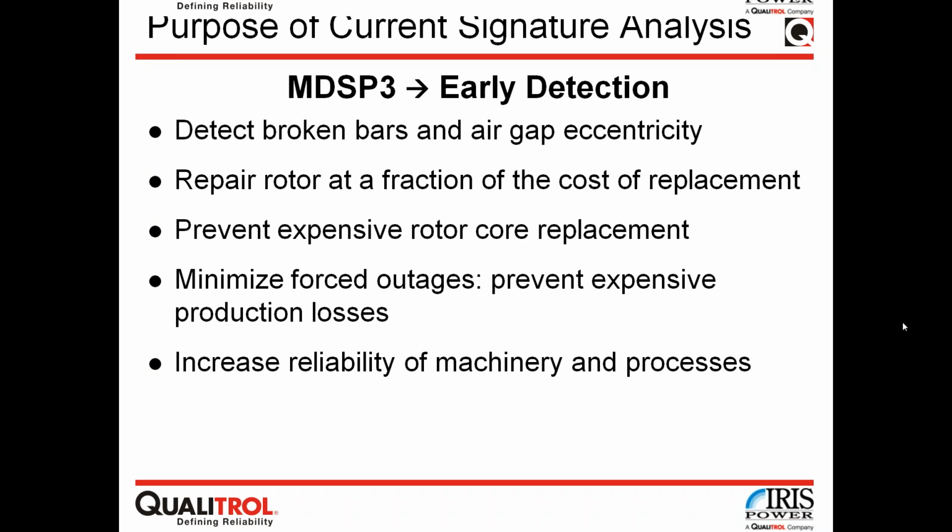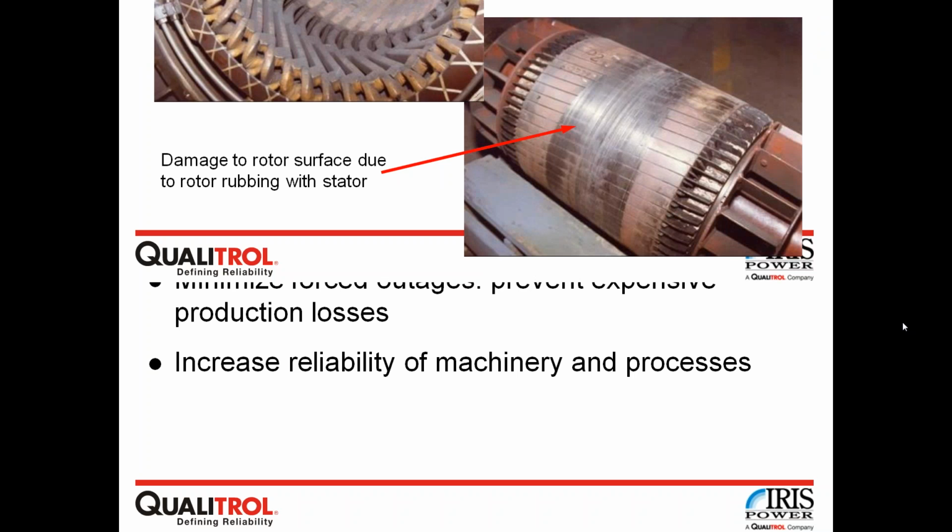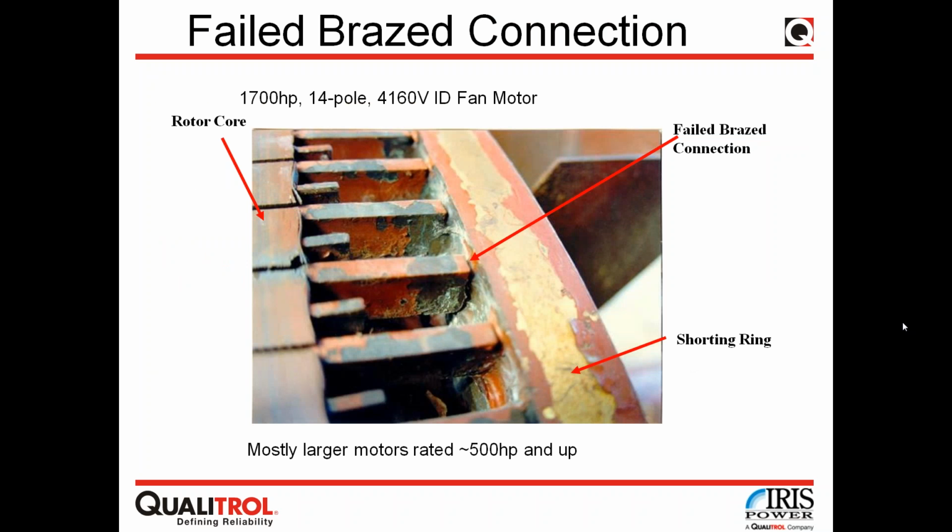Okay. It says offline rotor bar testing with an LCID tester. That's true. This kind of problem can be detected by offline testing. In a case where your failed connection or a broken bar is not visible, or it's not outside of the core like here, which is again the most frequent scenario, then an LCID, or an MCT, which is the LCID's younger brother, unfortunately not in the sales program anymore, a motor core tester, can be used to detect the location of the bar that is broken. So that is a simple test.